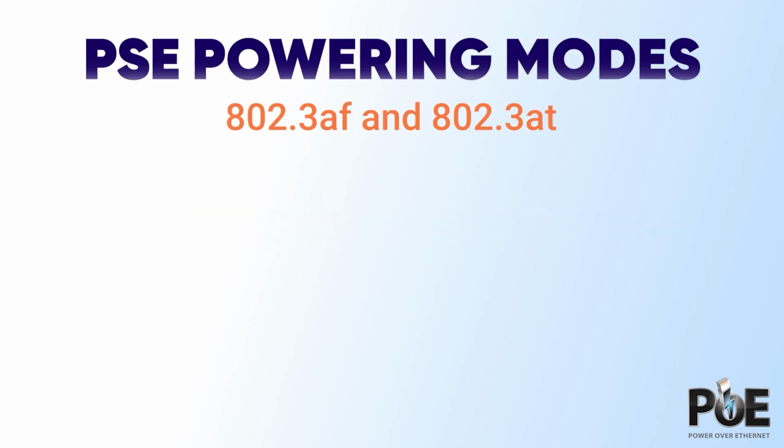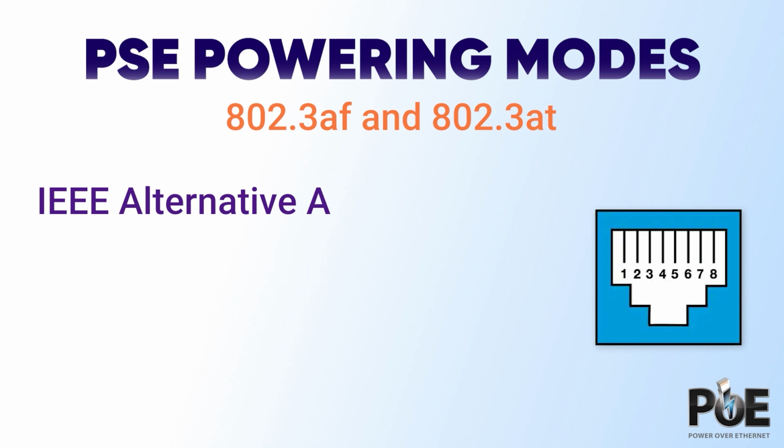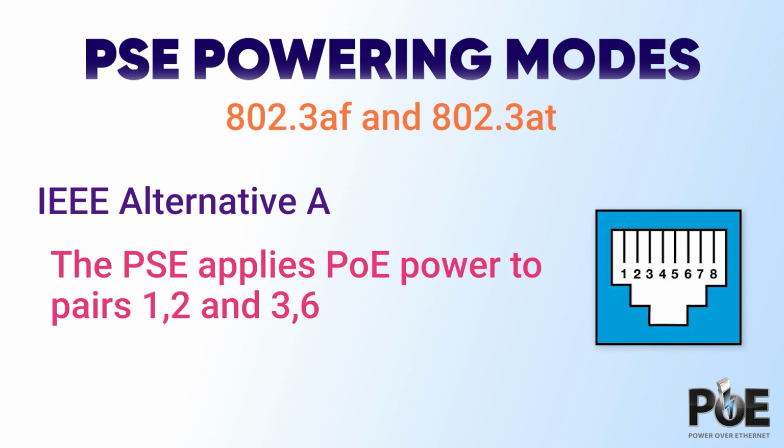The AF and AT standards support 2 different types of powering, Alternative A and Alternative B. Both alternatives use 2 of the 4 pairs in the LAN cable to carry the DC power. With Alternative A, the PSE applies the DC power to twisted pairs 1, 2, and 3, 6. With Alternative B, the PSE applies the power to twisted pairs 4, 5, and 7, 8.